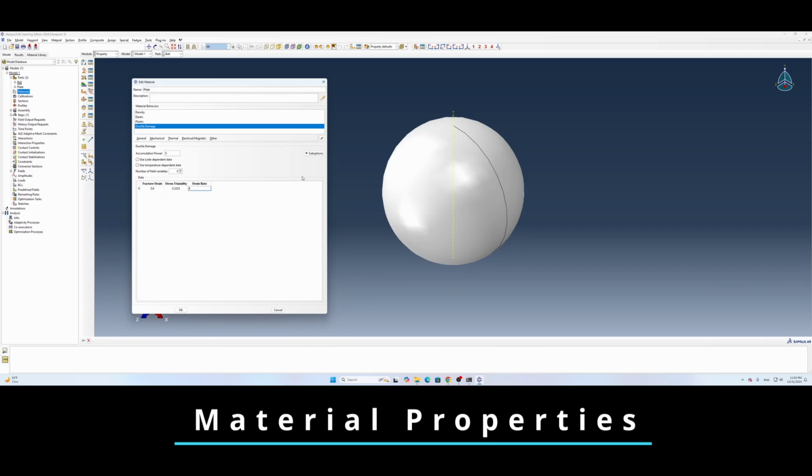For the strain rate, I'm going to assume that there is no variation here, so it's going to be 0. Then we have to go to the sub options, the damage evolution. For our damage evolution, we assume that everything is based on displacement, so everything is linear. And then for the displacement at failure, I'm going to choose 3. The number here is correlated to your mesh size. The mesh size I'm going to use for this model is 2.25. So that means that I allow my material to be stretched a little bit beyond its original size. Then you will have some failure. Then I hit OK.